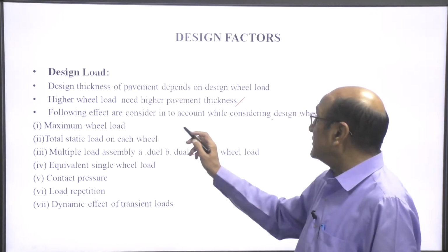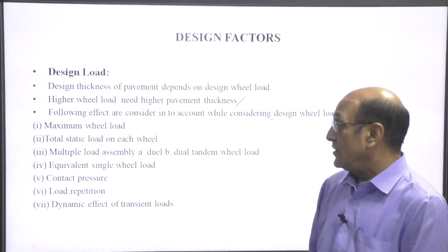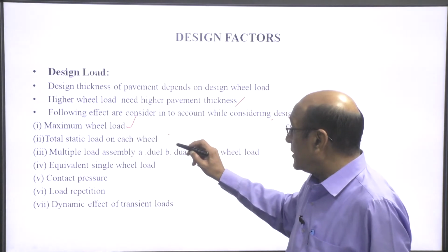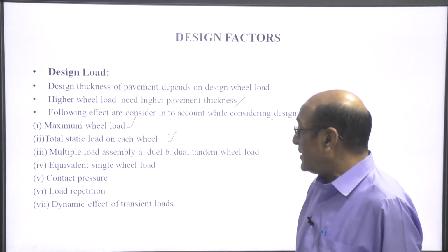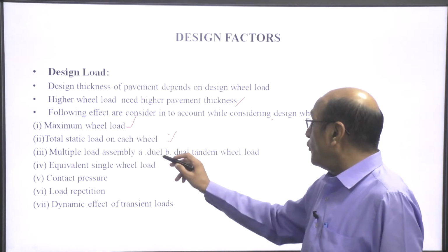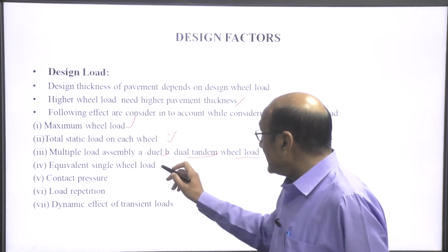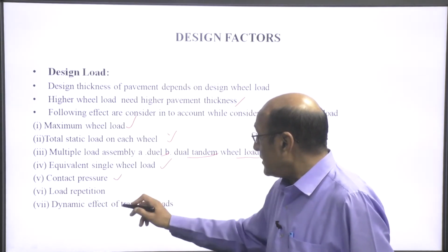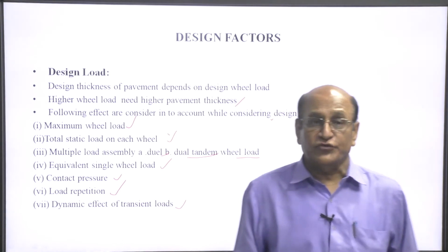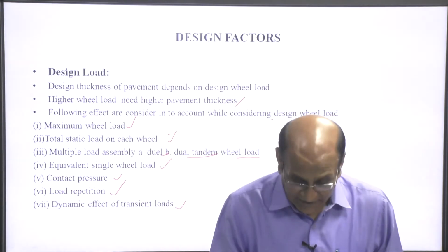The following are taken into account while considering the design wheel load: maximum wheel load, total static load on each wheel, multiple wheel assembly, that is dual tandem wheel load, equivalent single wheel load, contact pressure, load repetition, and dynamic effect of transient loads. So, these are the factors that are considered while designing.